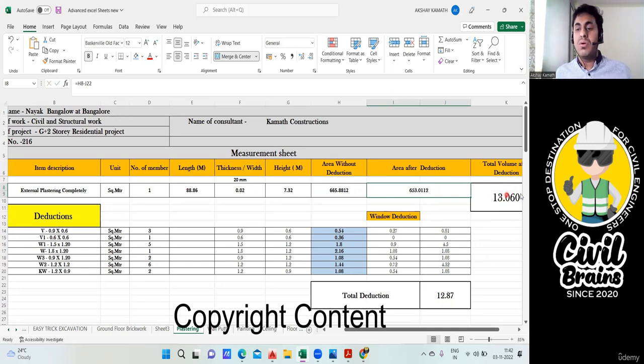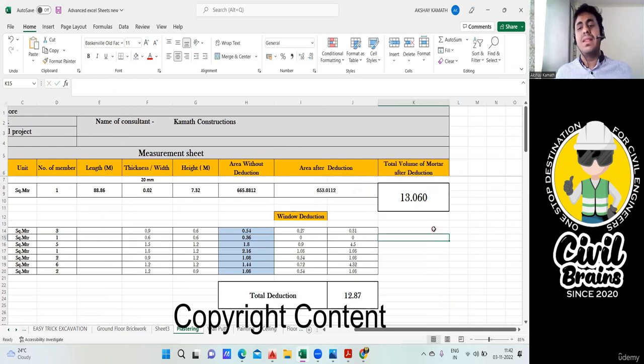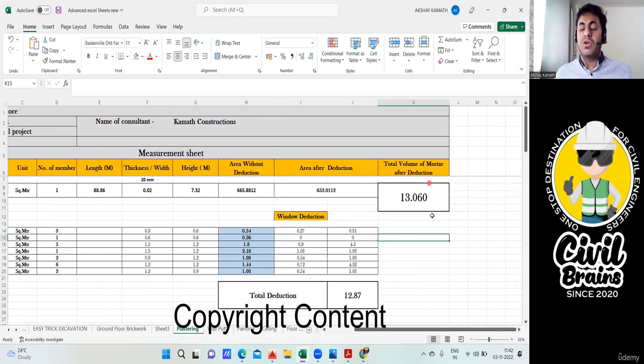So that is why what I have done, total volume after deduction. This is total volume of mortar. Mortar, that I'll teach you how much cement sand is required in the later part. Now you just do the quantity takeoff. Later in a single sheet we'll do all these things, how much quantity of cement, sand, aggregate is required for the plastering, for the brickwork and all those things. So this volume will help me later.